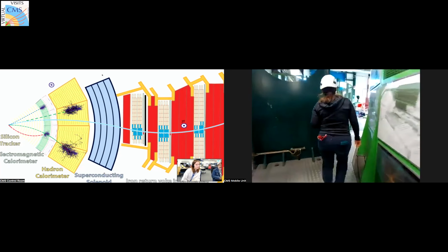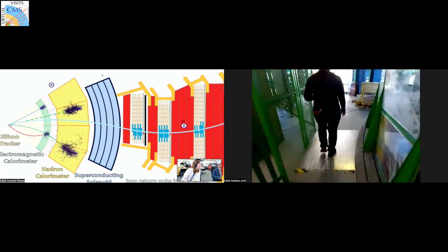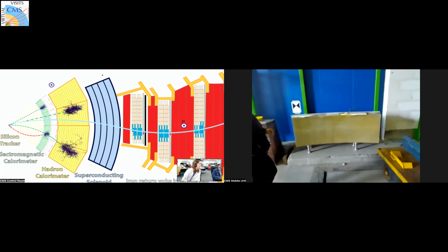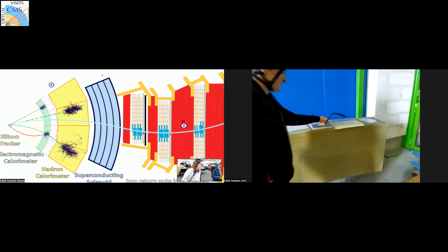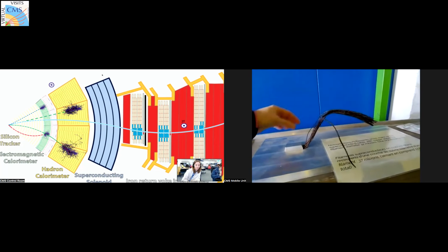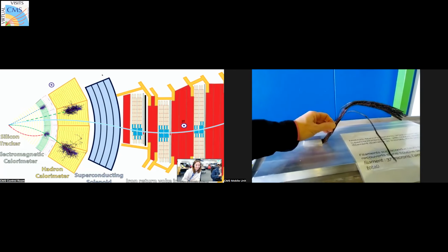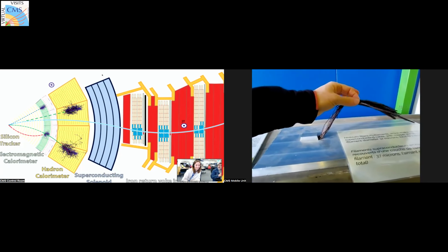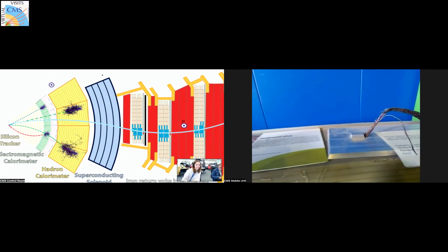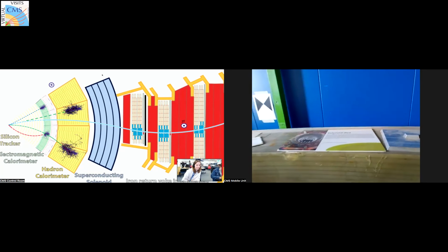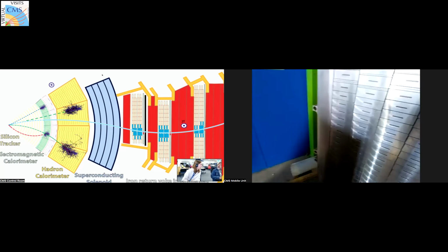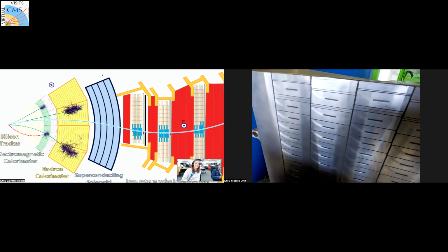What you can recall in the middle of that slab was the niobium titanium superconducting material, encased in copper for technical reasons. But what Noemi shows now, this Barbie hair, is the niobium titanium itself, with awful mechanical properties. That's why we have to do some tricks. But what you saw was a relatively small cross section, and that small cross section can carry 18,640 amps in order to create the 3.8 Tesla magnetic field.